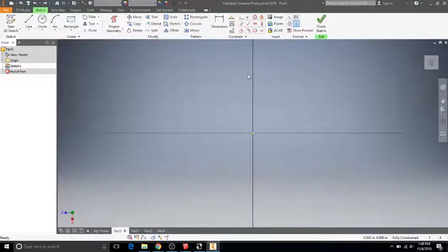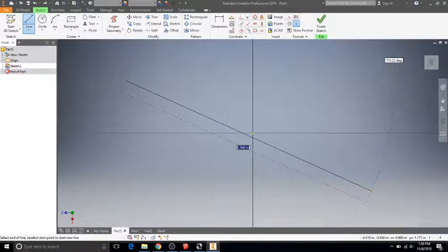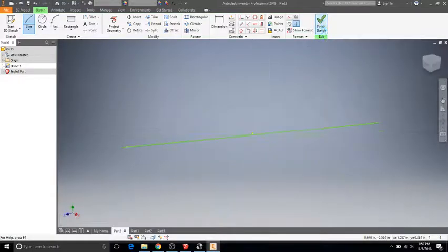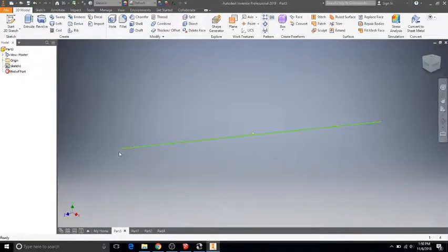This video is going to be going over Autodesk Inventor's use of the following tools: Sweep and Coil. So first of all, I just want to show you a random use of Sweep so you can see what happens. To use Sweep you need at least two things: a path, and I'm going to make just this random straight line my path, and you need a profile sketch. You take some sort of shape and you create a solid by passing it along that path, and the path can be straight or curved or follow arcs or what have you.